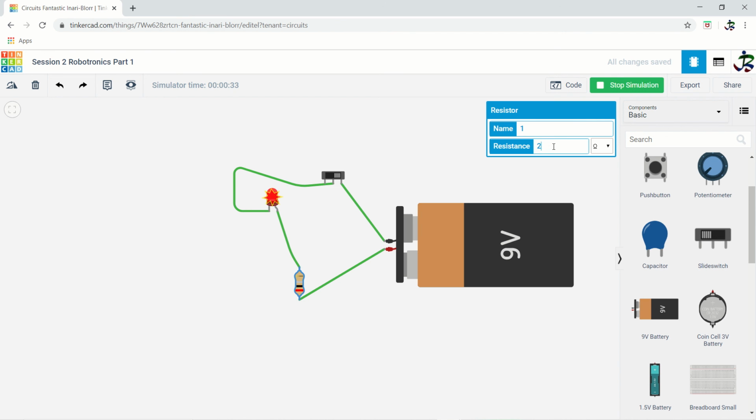So we have to increase the resistance to 200, it will not work, 300, it will not work, 500, it's okay. So at 500 we are not getting any message, so 500 ohm resistance is okay with it. So by this trial and error you can identify the resistance value, which resistance value will work for which circuit. Like here 500 is working for 9 volt and LED, so that's correct. So how to identify the value of resistance, that you understood now.